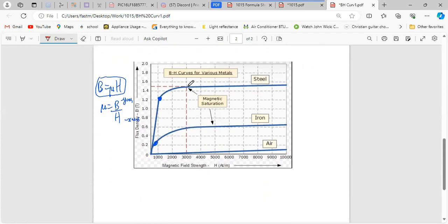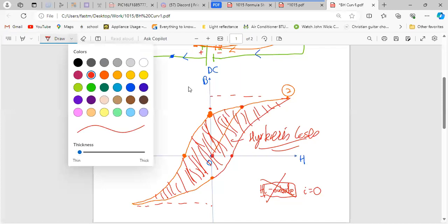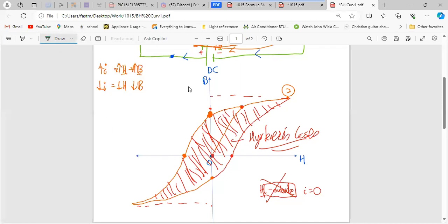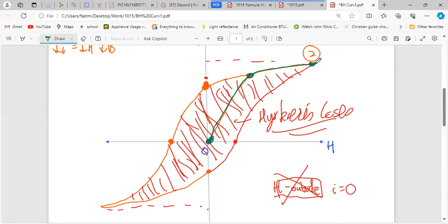And that is basically how the BH curve works. So this here is the BH curve, which is basically one piece of it. It went from here to here to here. I'm going to put it in green. So the hysteresis curve is from here to here to here, and the line I drew out is the BH curve. If I draw it over, it's basically just this. That is the BH curve. But when we talk about hysteresis, you continue the pattern in the upward direction, and you get one nice loop coming back to where you originally started.